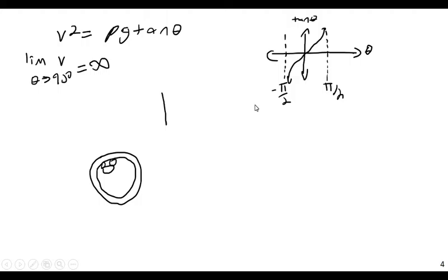So let's say I want to build a highway on the surface of the moon or Mars. What's the problem with that? Well, if I look at the required radius of curvature, it's v squared divided by g tan phi. If I'm on the surface of the moon, where the acceleration due to gravity is 1/6 that of the Earth, my radius of curvature is going to need to be 6 times what it would need to be on the Earth to make it through a banked curve.